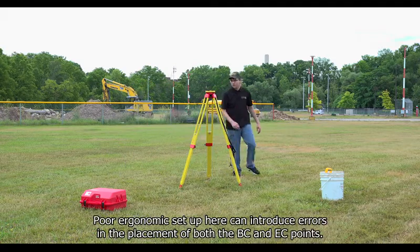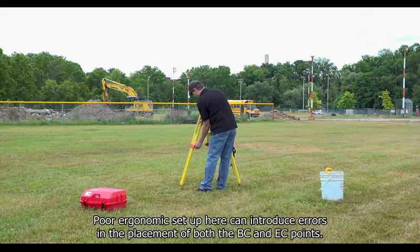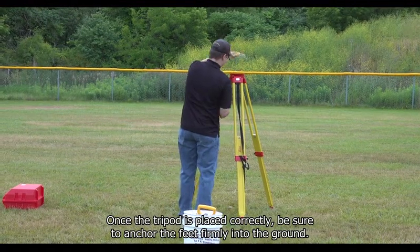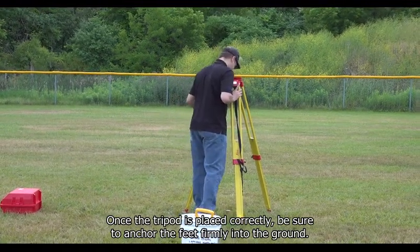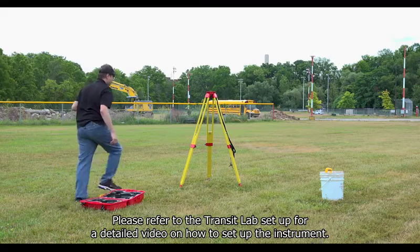Poor ergonomic setup here can introduce errors in the placement of both the BC and the EC points. Once the tripod is placed correctly, be sure to anchor the feet firmly into the ground. Please refer to the Transit Lab setup for a detailed video on how to set up the instrument.